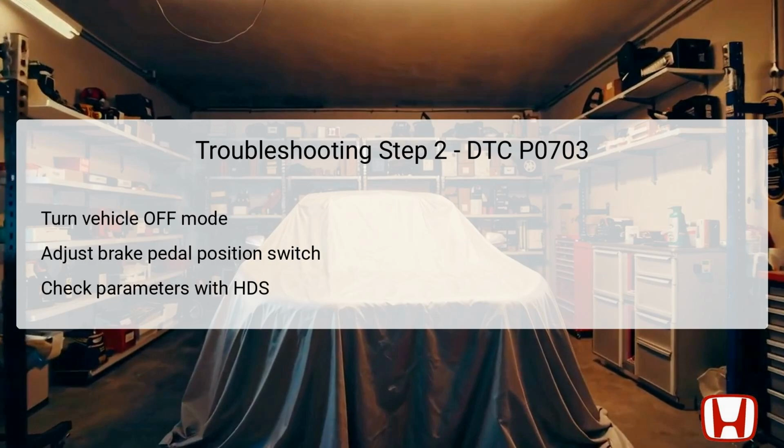Similar to the first step, the expected results should show the cruise brake and idle stops as close. If the conditions match the anticipated threshold, the fault may not be duplicated. If not, you would then escalate to the third troubleshooting step for further diagnosis. Proper adjustment here is essential for accurate signal transmission and overall safety.